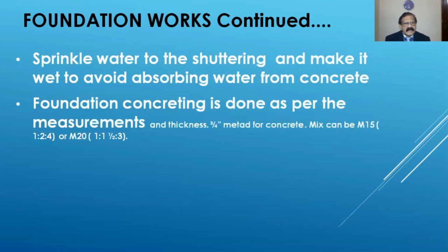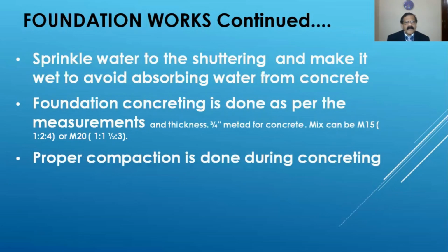After sprinkling water, you will be doing the foundation concrete based on the depth given in the drawing. For concreting, you will be using M15, that is 1:2:4, or M20, which is 1:1.5:3. When doing the concrete, you should be very careful to see that proper compaction is done.